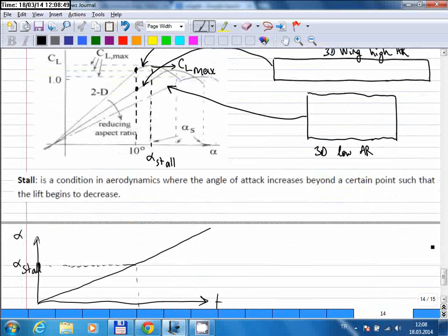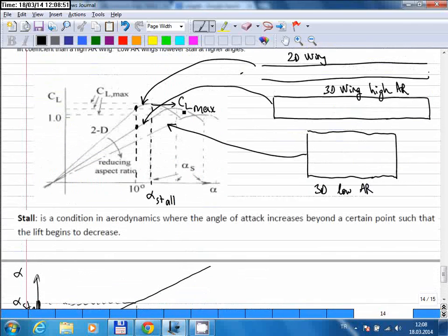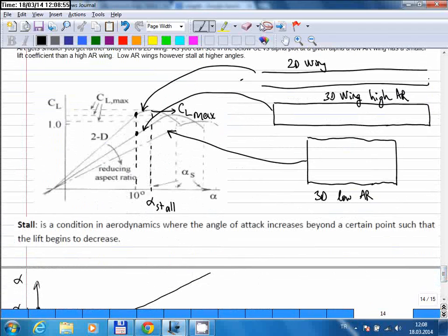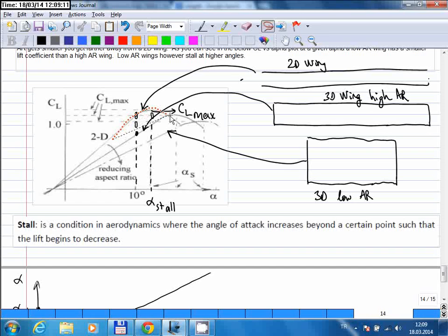Okay, so apparently in the previous years I also talked about stall on this graph. So let me just do that here as well. So if you look at the data here, the original data, you see that your lift coefficient increases with the angle of attack, right? And then at some point it makes a peak and starts going down again. And the point where it reaches the maximum possible value is called the stall condition.